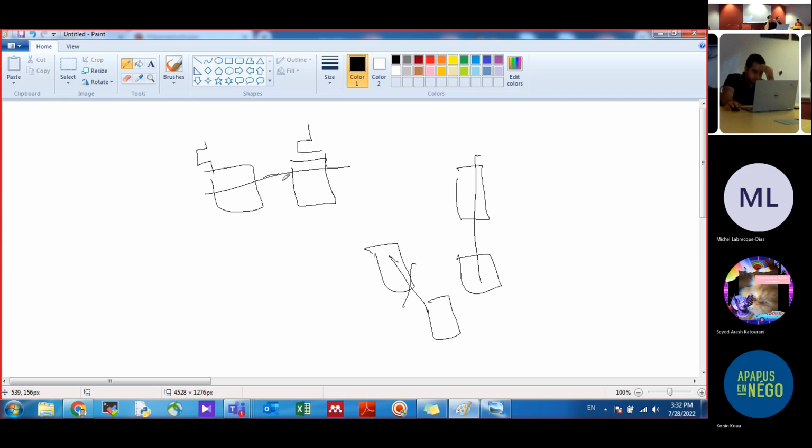But in all cases, the current goes in this direction. You can put your transistor not exactly at the same X and Y axis, as long as the current flows in the same direction. Is the current direction only important on symmetric systems like a differential pair? I know about that one, I don't know about others.